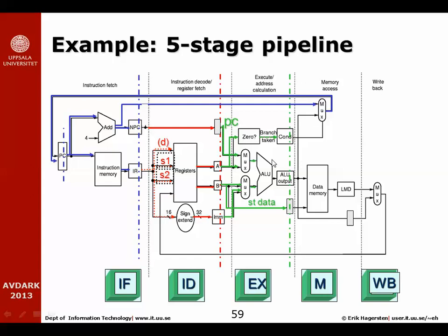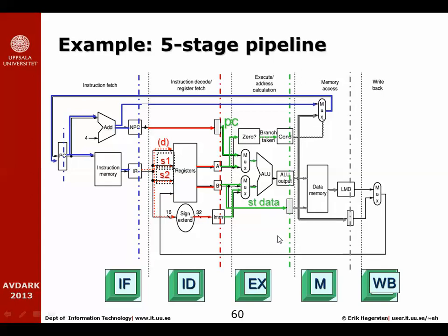So now the ALU can perform its work. It could be adding 2 register values together, could be calculating the next address we need to access from memory, or it could be calculating the next program counter that we need to make the execution from. That value that is produced by the ALU is put into this ALU output latch here. At the same time, when we perform store operations, we also need to store the value from one of the registers, the value that we're going to write into the data memory, in the latch here, so it's ready to go.